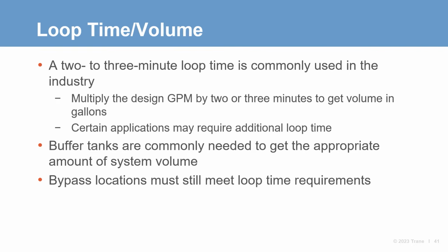Of course, some applications may require longer loop times. A process load with tight temperature requirements or an air-to-water heat pump design that incorporates defrost mode are typical applications in which more loop volume should be considered. Please reference the specific requirements of your application.